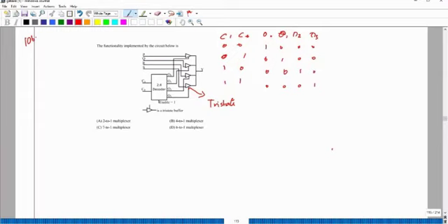So okay, you see, after that you are having only 4 inputs. Okay, you are having 4 inputs and you have only 1 output. Okay, so if C1 and C2 is 00, this O0 only gets selected and P will reach the output, right? P will reach the output.